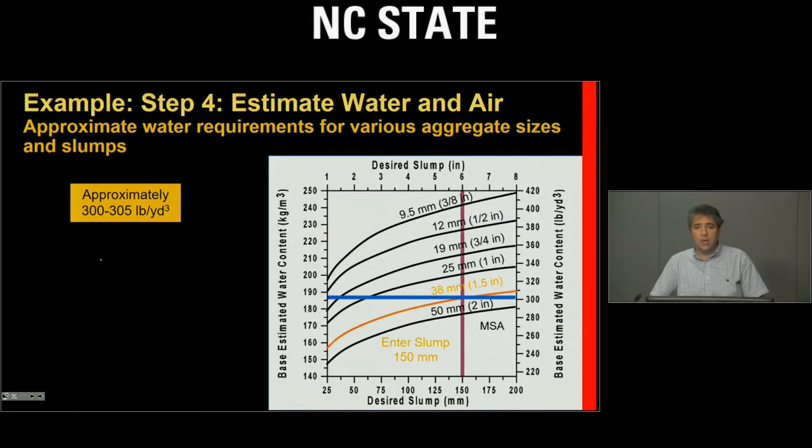All right, let's go to our particular example over here. We said that we are given 1.5-inch maximum aggregate size. And in our particular example, we will go ahead and select the 6-inch slump. We will drop a line over here from 6-inch. In this slide, the lines are straight, as opposed to the previous slides that I was trying to draw and did not succeed.